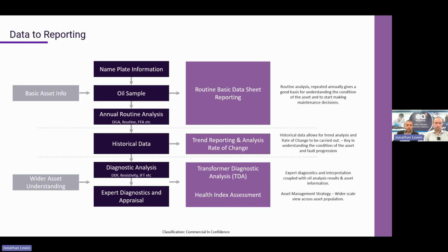Going another layer down from that, you've got your diagnostic analysis. So this is more in-depth laboratory testing: dielectric dissipation factor, interfacial tension, particles, corrosive sulfurs, a whole lot of other laboratory tests that go to the next level of determining what is the condition of that oil and what action is needed.